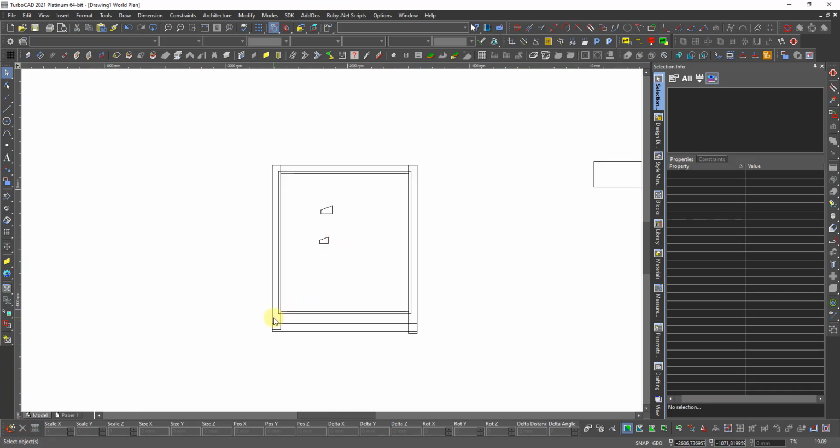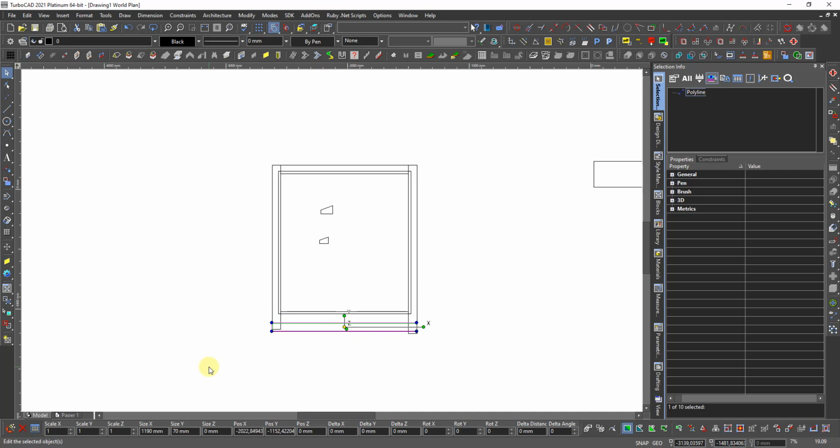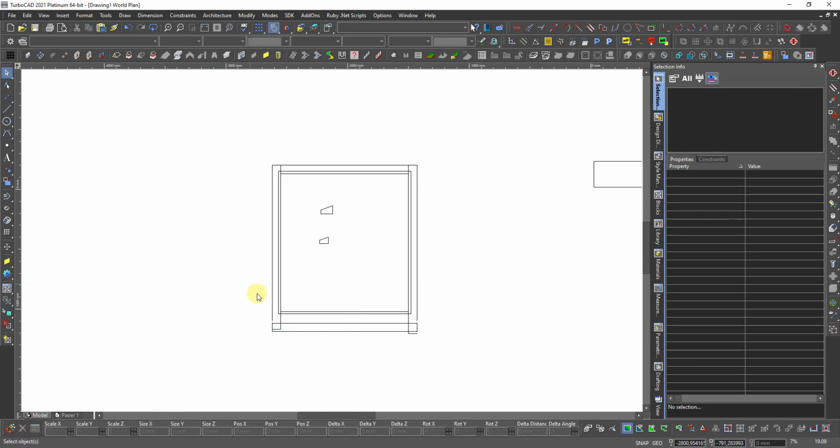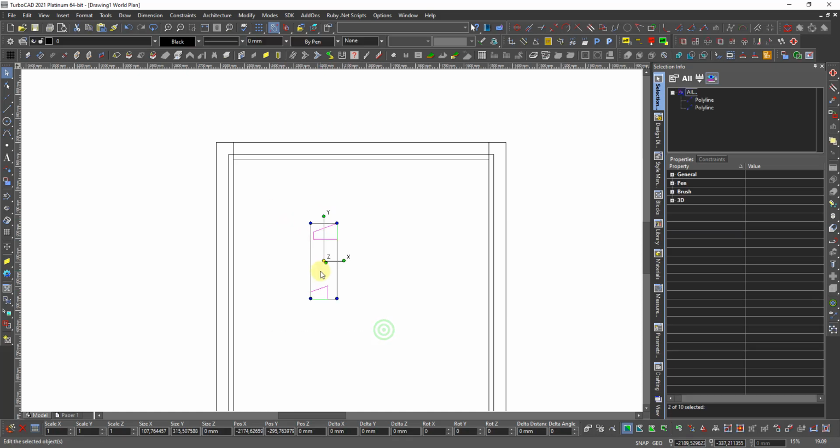This should cover from here 2 centimeters outside on both sides. So then it will be this length, 1190, then 5 centimeters extra on each side, then the window is, plus 20 here and 20 there. So the 1190 plus 40 is 1230. Then I select this, and I go to 3D section here, and I say it should be solid, and the thickness should be 1230.